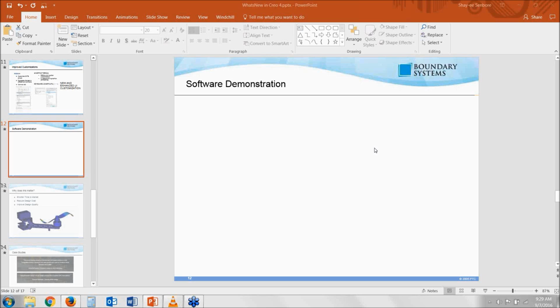And the question was asked, can you also seamlessly print with non-Stratasys printers? And for that, right now, it's no. So basically, with the Stratasys printer and Creo 3 and also 4, currently you can connect the printer to your Creo installation, so that you click print, and then it passes the information straight to the printer without the need for Object Studio typically in the middle.